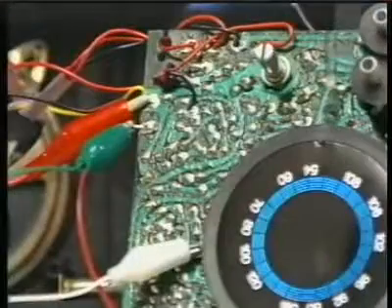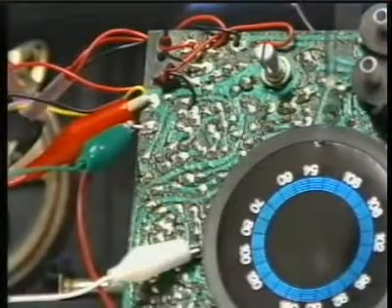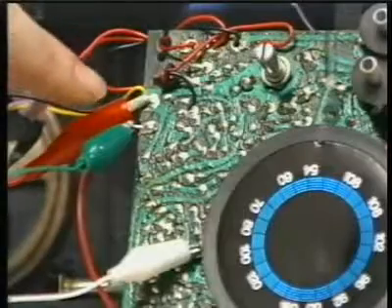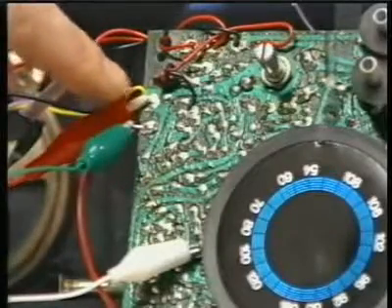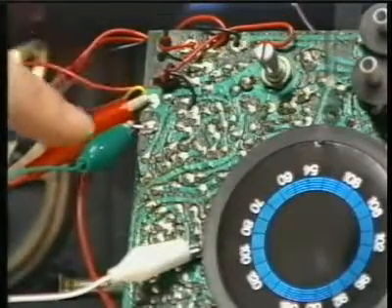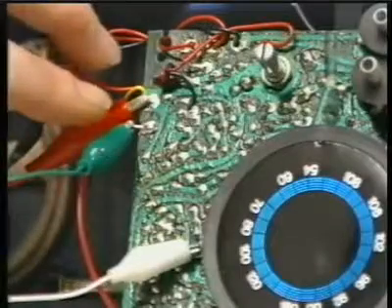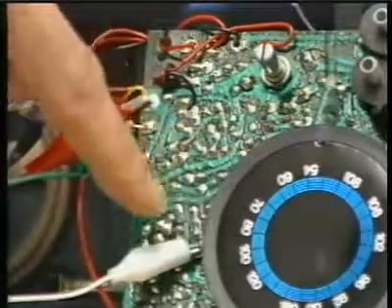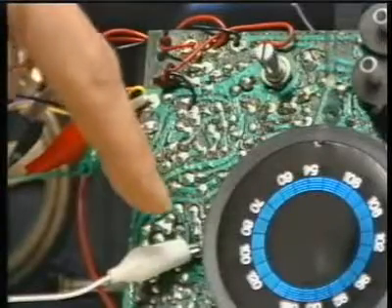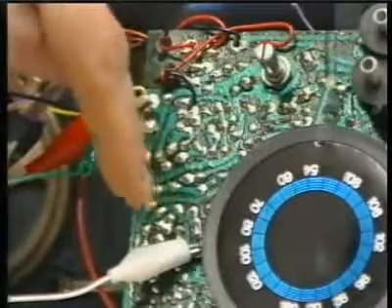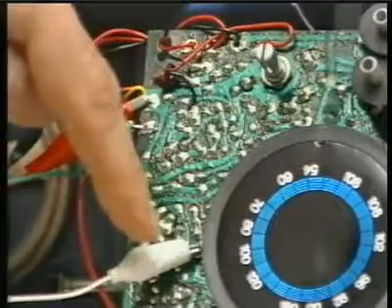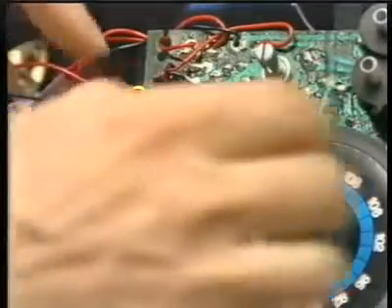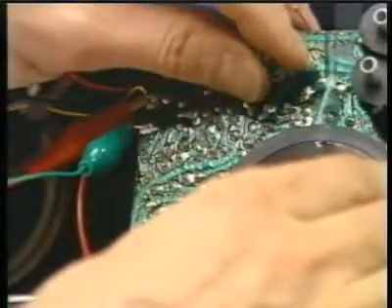So I guess Sandy has some probes on the RF input and a ground. That's right. The red lead here is a ground. It's common for both the signals we'll be looking at. This is the audio. We're actually looking at the signal going directly into the speaker across these two leads. And then this probe down here, which I found by hunting and pecking, is the IF signal, the intermediate frequency signal, with a station on it that I'll now try to tune to get something that sounds reasonable.